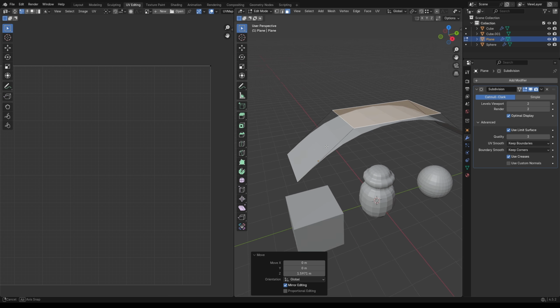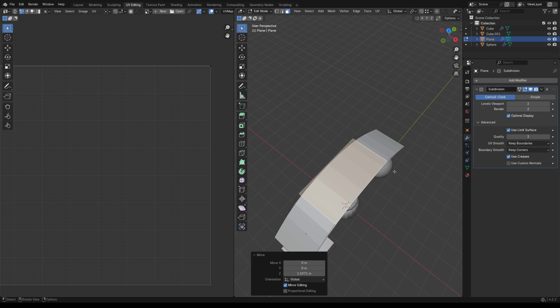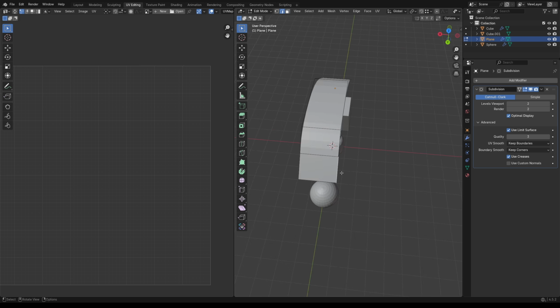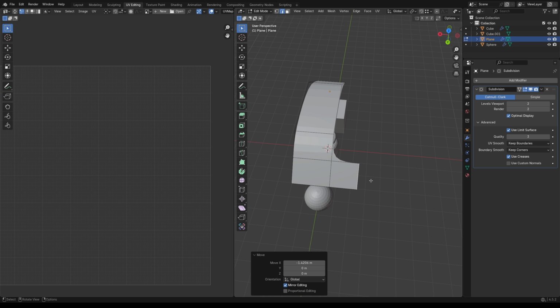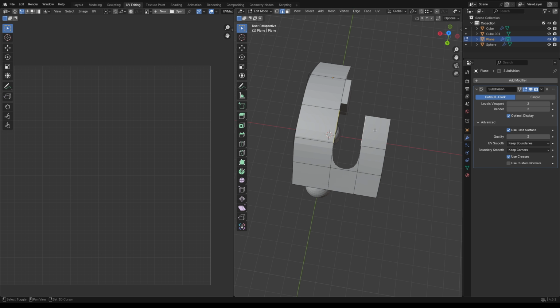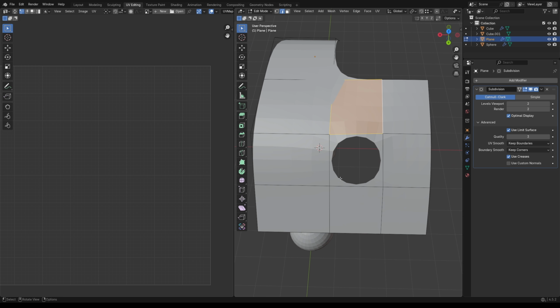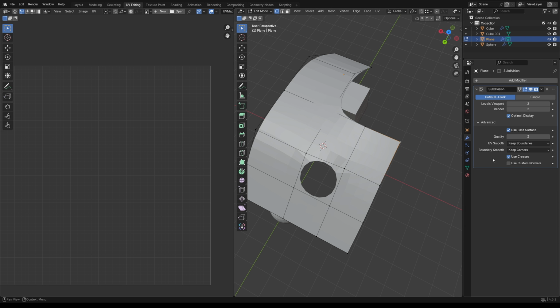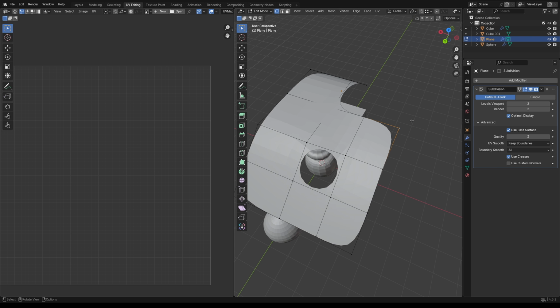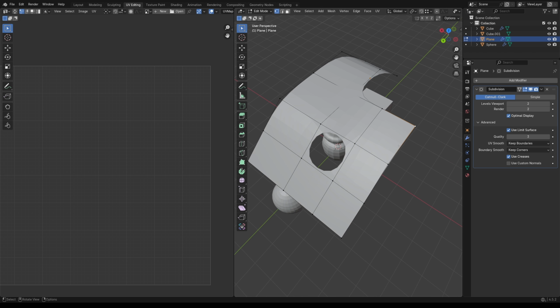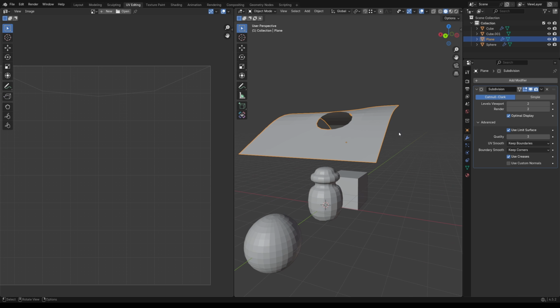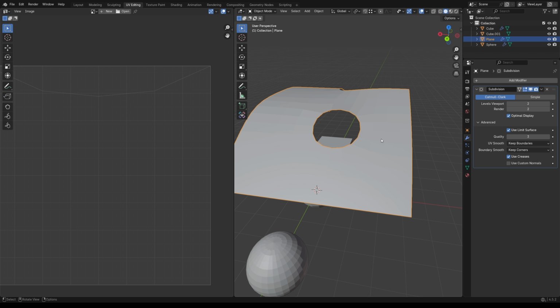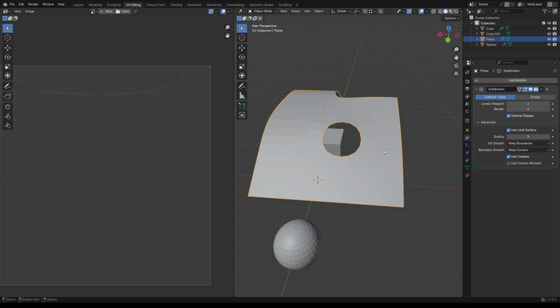And that the curvature is something that I often need, but the corners I need to keep. And that's pretty much it about this one. The only thing I need you to look out for is that in this case, many people are creating holes like they will extrude and do the circles by just deleting the polygon, which is going to make the circle, but the outside circle often stays like this. If you boundary smooth all, it will smooth out. But if you keep the corners and you are using this on already prepared mesh, this is something that could happen to you, and maybe you would notice, maybe you wouldn't, depends on how complex your model is, but that's really just something to look out for.